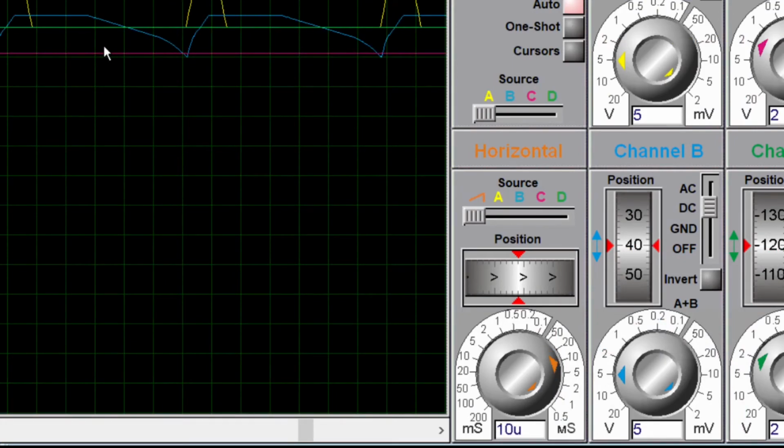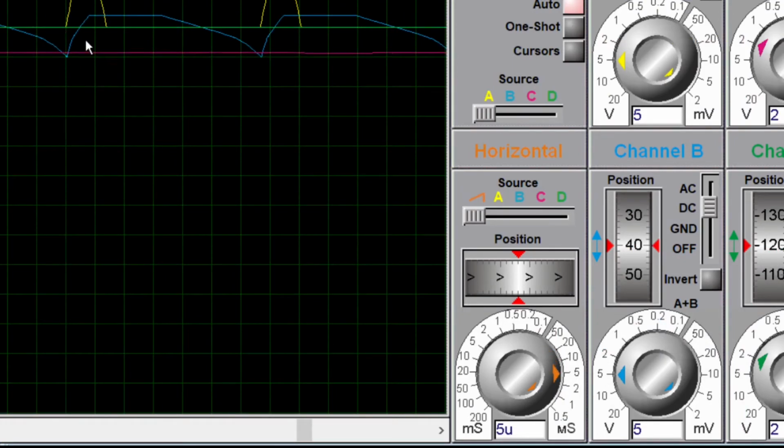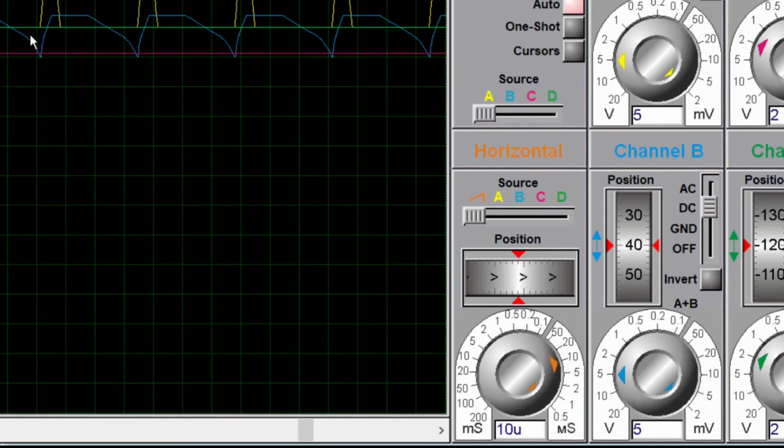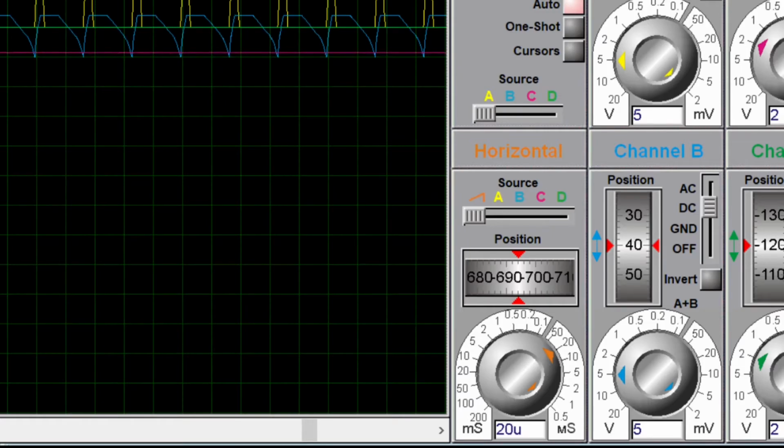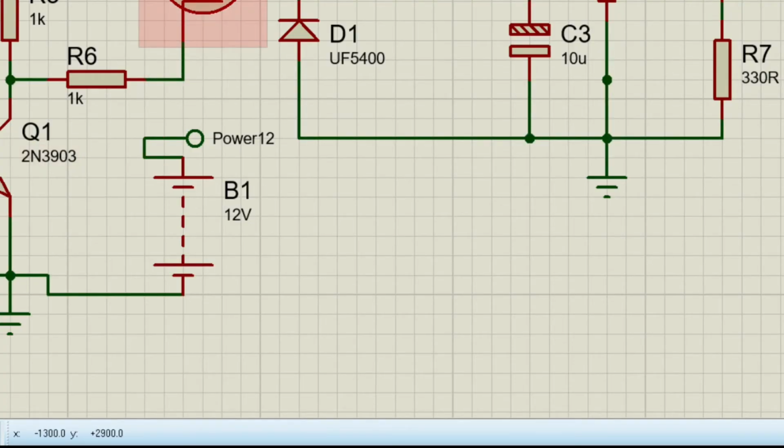You'll see now that the MOSFET itself is not working correctly, and the output voltage is 10 now, and it is getting bad for the MOSFET, because this MOSFET is not able to switch at higher frequencies. So to solve this problem, we will replace this MOSFET with another MOSFET which is able to switch at higher frequencies. Let's see that this IRF 4905, we will remove it from the circuit, and we will use actually